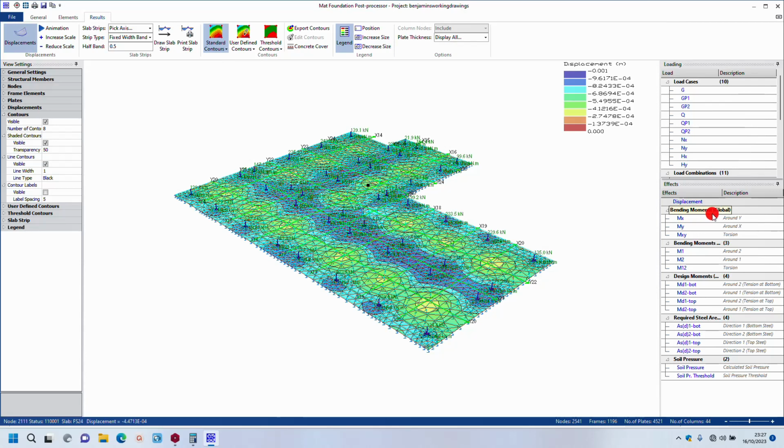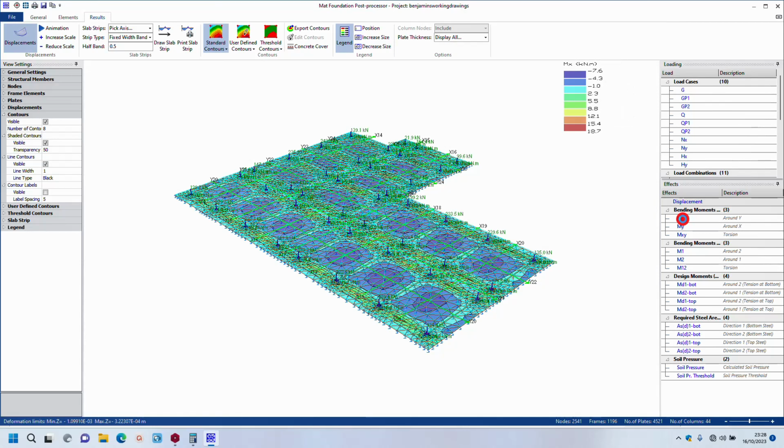Now this is bending moment. We'll come to this place. Make sure this mouse is touching. You can see my MX, you can see a line. If I take this mouse off, no line. If I bring back the mouse, you can see a line appear. You left click on it and wait for it to load. Now if you click on it, put your eyes here. This is the minimum, this is your least moment, and this is your maximum moment. And mind you, your M max is always more than your M min, so always put your eyes on this place. Now we are done with MX.